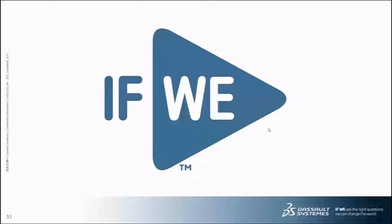So you need to switch to cyclic loading plasticity models, and that by itself is a very large topic, which I can't get into today, but the terminology there is kinematic hardening. So if you're interested in this idea, you can look in references or do a Google search on kinematic hardening plasticity and find out more about that.